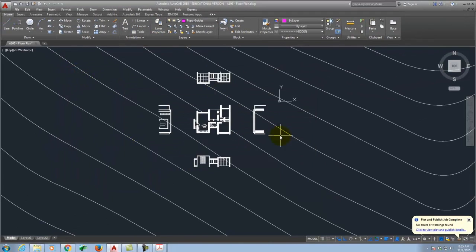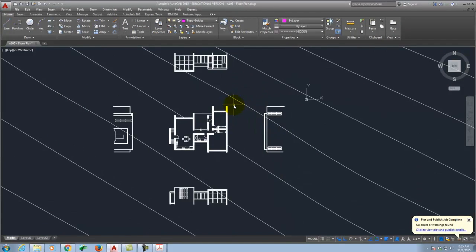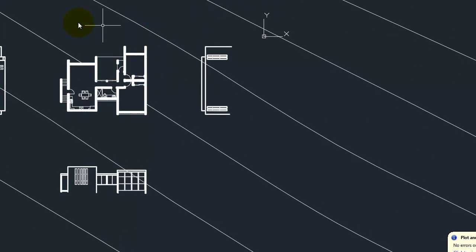Now I'm going to create guides that are pulled off of the topo line. If we look at my floor plan here, I have a contour there, a contour here, and a contour here. I know that they're all 1 foot apart. So this one starts at, call it, level 0. This would be plus 1 foot. This would be plus 2 feet as I go up in space.